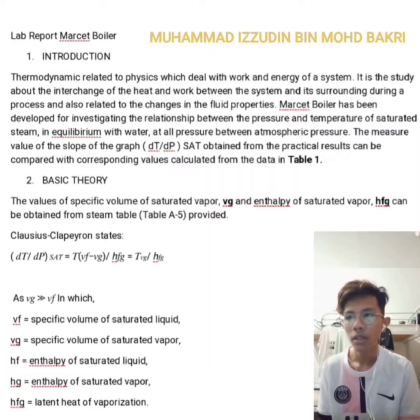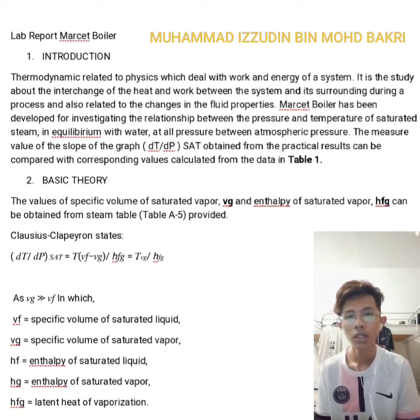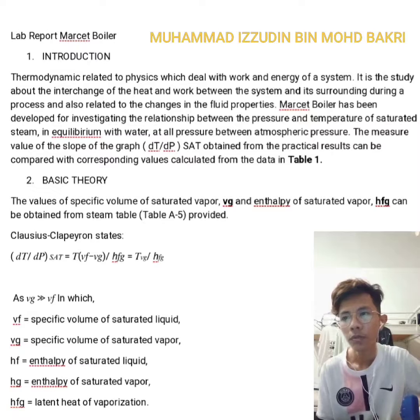The Clausius-Clapeyron equation states delta T divided by delta P saturated equals T multiplied by (Vg minus Vf) divided by HFG, which is equal to T Vfg divided by HFG, where Vf is the specific volume of saturated liquid, Vg is the specific volume of saturated vapor, Hf is the enthalpy of saturated liquid, Hg is the enthalpy of saturated vapor, and HFG is the latent heat of vaporization.